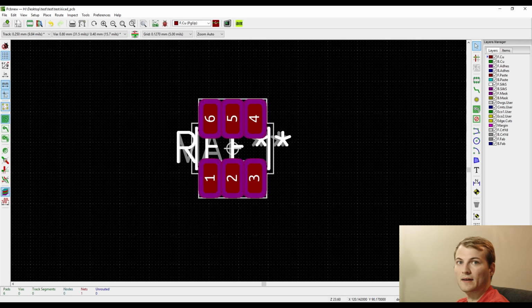So that is the way that I handle the footprints for common packages. If it's a manufacturer-specific footprint, for example a lot of H-bridges or MOSFETs have unique thermal pads on the bottom, those you still have to make the regular way with KiCad. But for 90 to 95% of all the footprints, I use the library manager to make them, and it makes all the footprints IPC compatible. So that sums up this video.